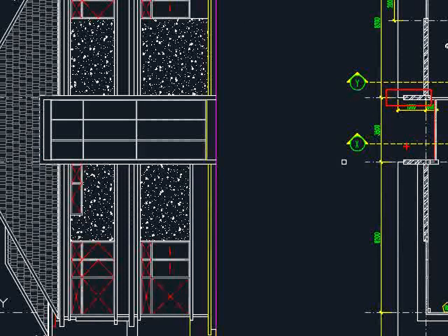I believe this part you cannot do it with the brick wall. Most likely this is going to be an RC wall, where you're going to have reinforcement bar penetrating through different floors of the building until you reach this level, and you have a slab also reinforced with concrete, so that this entire piece of architecture features are fixed to the structures. This design is quite nice. It looks attractive to the clients, and it is the responsibility of the engineers to ensure this is stably constructed.